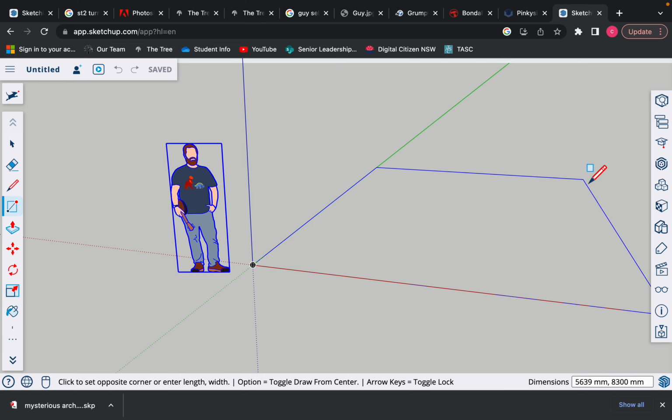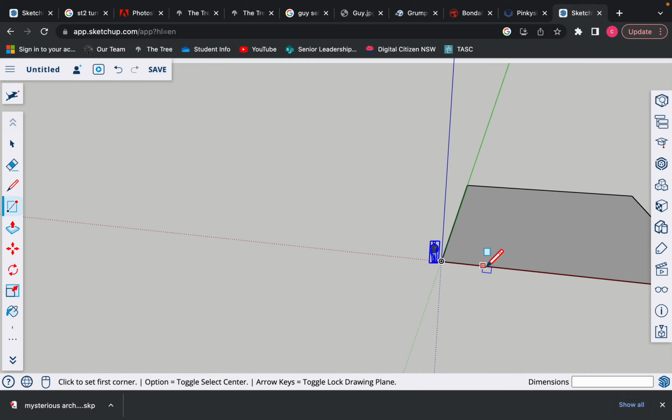So you'll see that without clicking again, down here in the bottom right hand corner, it's got the 2 dimensions. So it's got 5409 and 6839. You can see down there. I can't move my mouse to show it to you, but what I'm going to do instead is just simply put in the dimensions. So I might make my block of land 20 meters, so that'll be 20,000. So I'm just typing it in, and it's automatically going into that dimension box down on the bottom there and I might make it by 30,000. Okay, I'll type those in, hit return, and it's made my block to size.